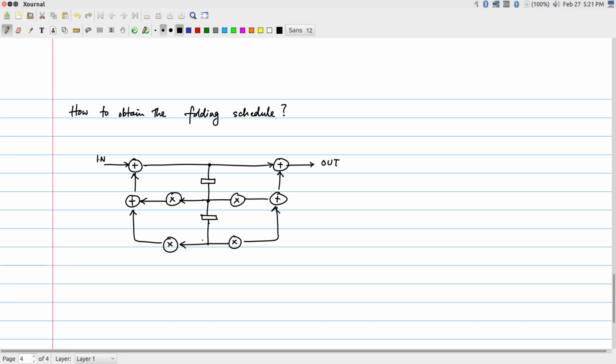But if you look at it, it's a bit more tricky than that, because what has happened over here is the IIR portion, the feedback, is in the left hand side, the earlier part of the diagram, and the feed forward is in the later part, right? It turns out that this is most easy to understand if you look at it in terms of the signal flow graph and do that transposition operation that I had mentioned somewhere in the earlier while we were talking about signal flow graphs, right? That's the easiest way to sort of obtain this structure, right?